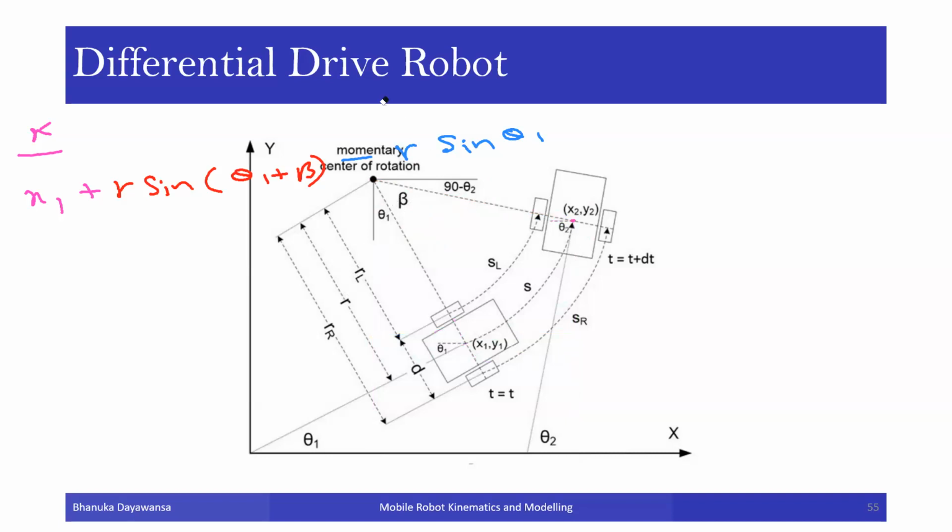So the y terms are simply this, right? We want to find this distance from here to here. This is the final pose of the robot. So the y term, of course, we know up to this point. This is y1, no problem there. Plus, we have to get this distance. Now to get this distance, we can simply find it the same way that we did earlier.